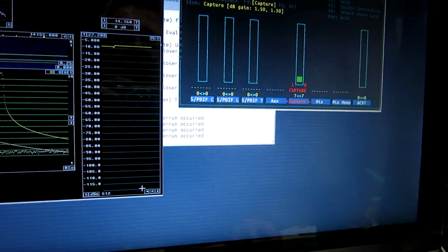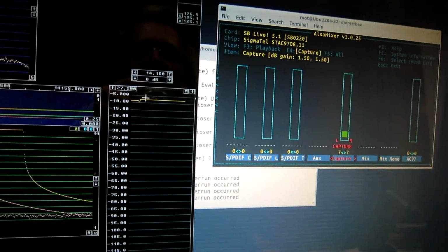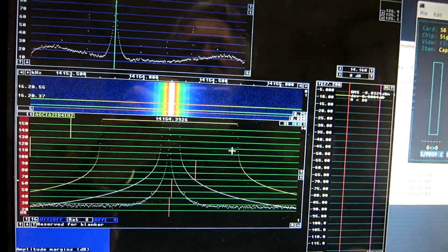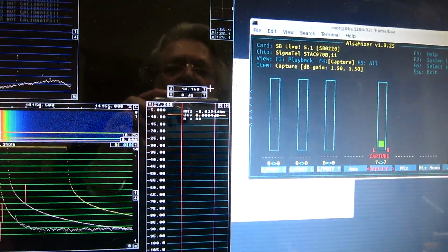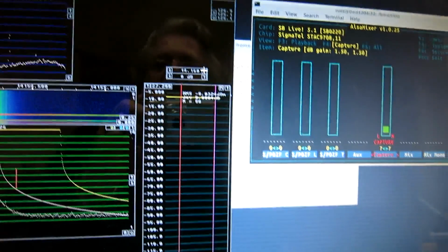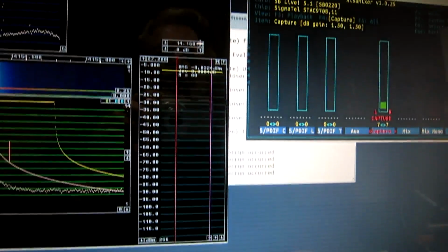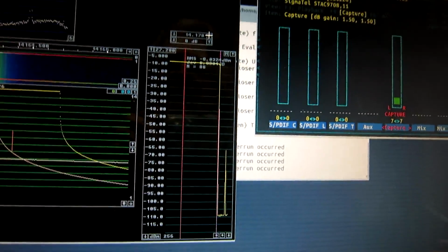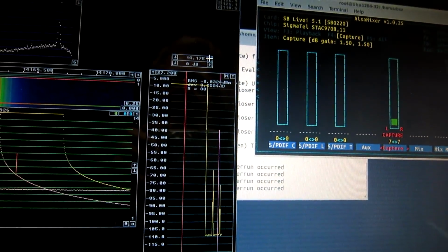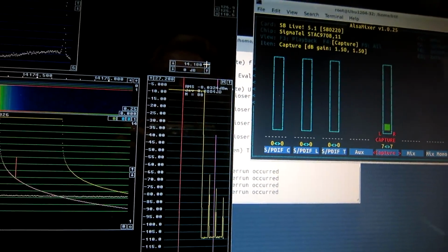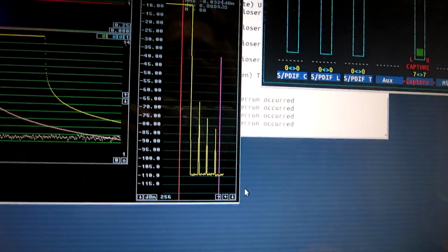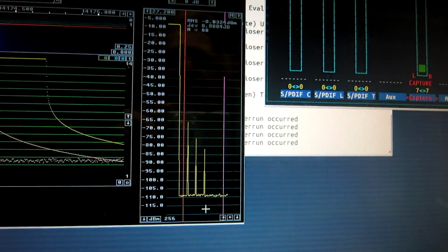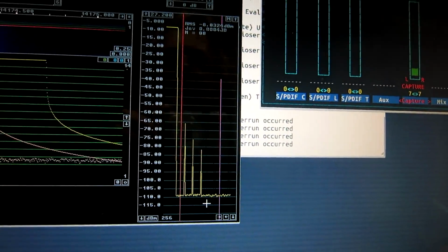Well, I run it a little bit faster. -8 dBm. Bandwidth 1 kilohertz. And I'm looking for reciprocal mixing, so I step the frequency in steps of 5 kilohertz. 5, 10, 15, 20, and the frequency separation seems to have no effect. The noise floor is at the same level, and I check that level.